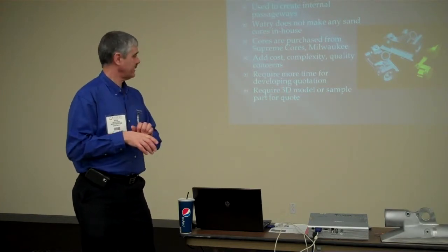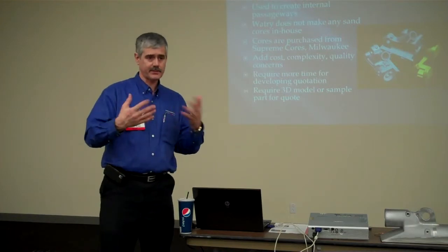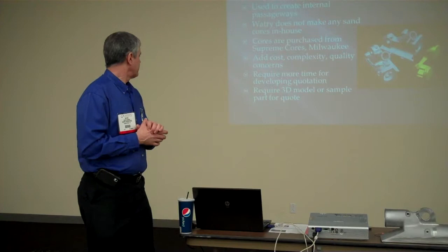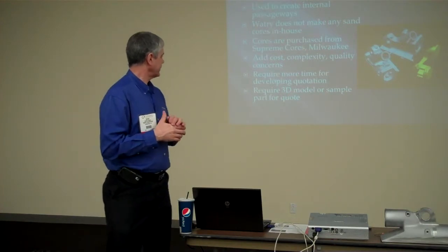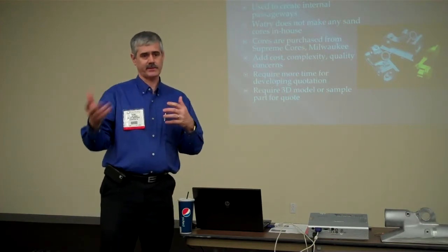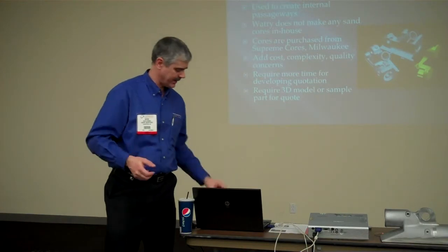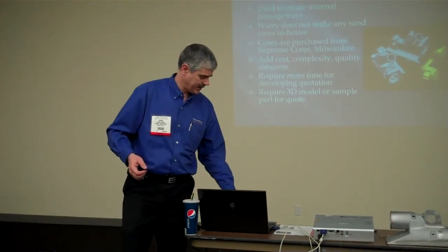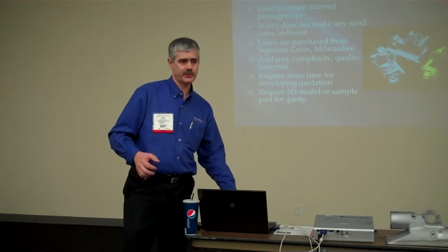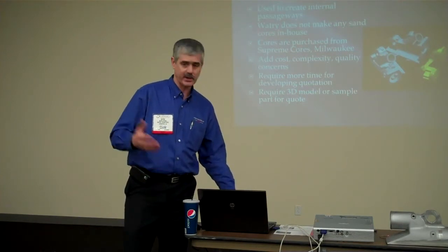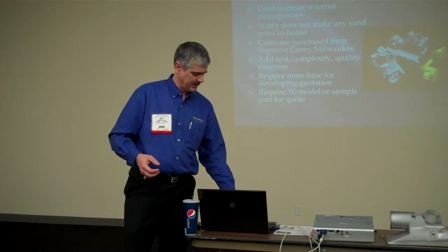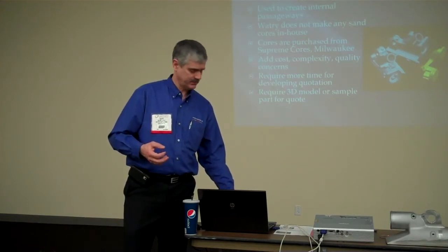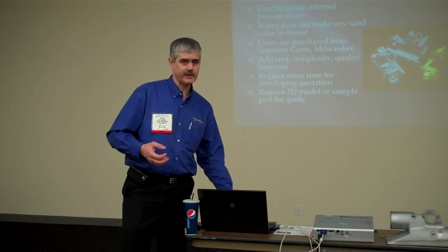Cores do add complexity and add a level of quality concern that has to be taken into account in the process FMEA. It does require more time. If we're quoting a part for you that has a sand core in it, it takes me longer to get that done because I have to go to somebody to get pricing on it. And we really need 3D models anytime there's a sand core. Most of you are on some kind of a 3D solid modeling system, and sending us a STEP file, an IGES file, or Parasolid is really necessary to look into sand cores.